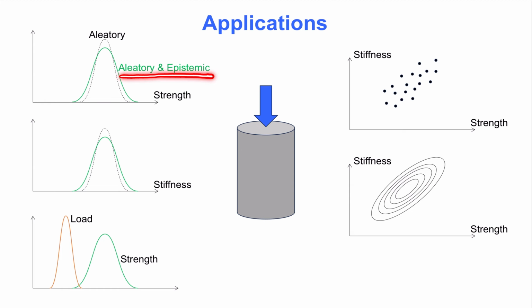Measurement uncertainty in how the strength and stiffness is measured is aleatory, unless we change the entire test setup. Model uncertainty in a linear elastic structural model is epistemic because we can improve the model by introducing nonlinear finite element analysis. Some argue the philosophical point that all uncertainty is epistemic. One proponent for that viewpoint is the so-called Laplace's demon, which suggests that all uncertainty can be reduced if we just measure and model everything perfectly. Such a viewpoint is unrealistic in engineering. For us, there will always be some uncertainty that cannot be reduced.